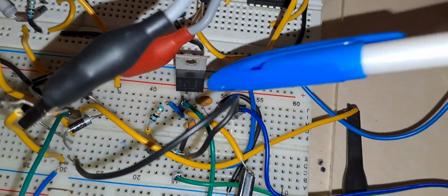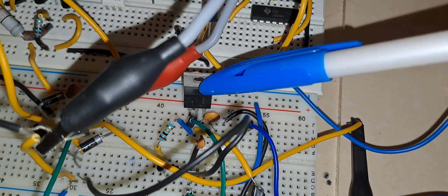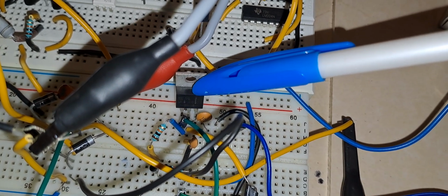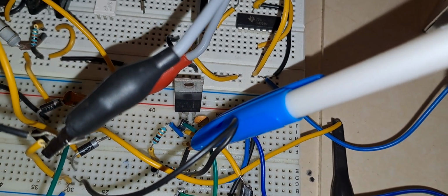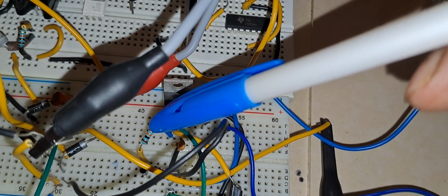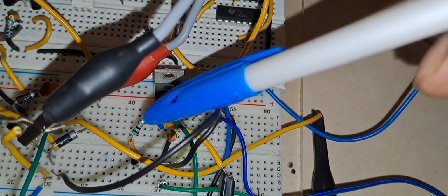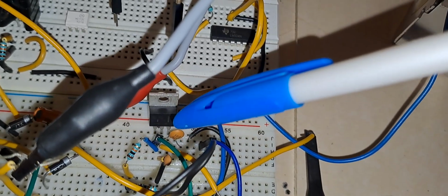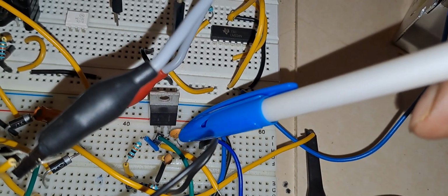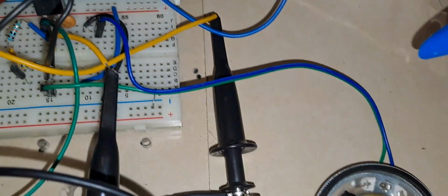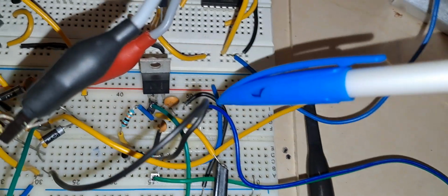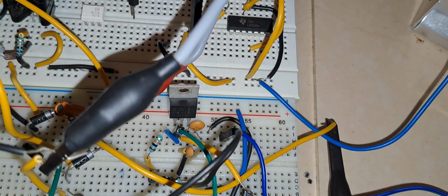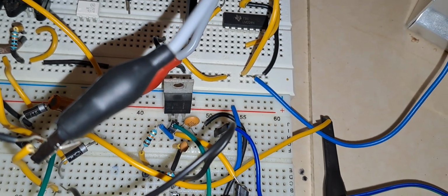You can see here, this is the envelope detector. This is a high frequency diode, and there is a capacitor below with a 10k resistance, 20k resistance actually. So it is forming the demodulator. The output of the demodulator is fed through this small capacitor to this speaker. Whatever signal we are feeding, we are expecting to get back the same signal.